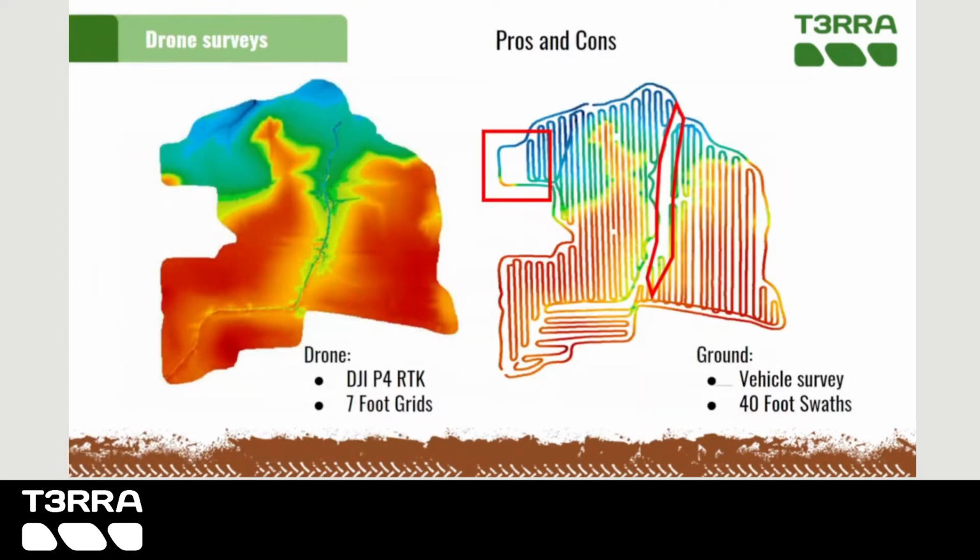We are seeing more and more elevation data acquired with drones. Drone surveys can be beneficial when areas cannot be surveyed on the ground, such as waterlogged areas or ditch bottoms. This can result in a more accurate elevation map by capturing all changes in elevation, as its pass-to-pass swath is closer than a ground survey, which can result in a large difference in dirt balance totals.